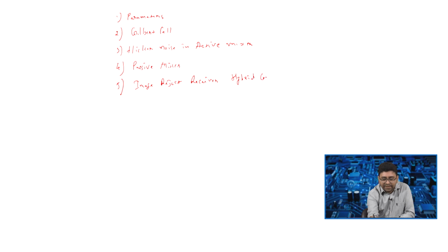This design will also be useful when we are designing a configuration for sub terahertz or terahertz applications, because generating a 90-degree phase shift is difficult by using the normal RC at very high frequency. So, you can use a hybrid coupler approach to design the quadrature mixer. We also discussed the quadrature mixer.